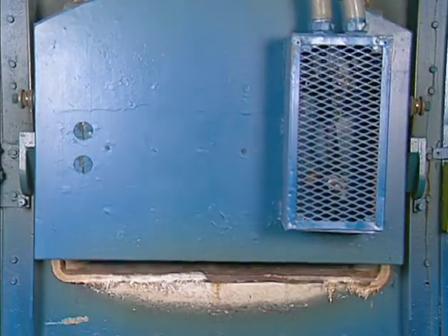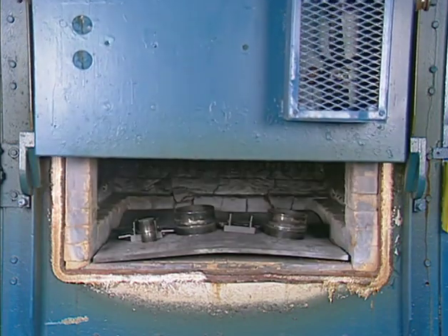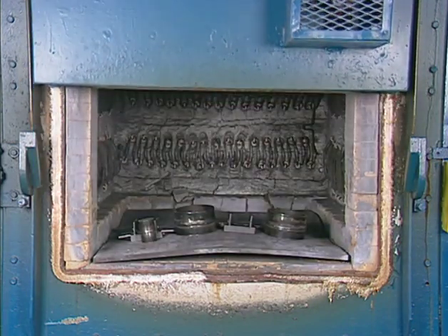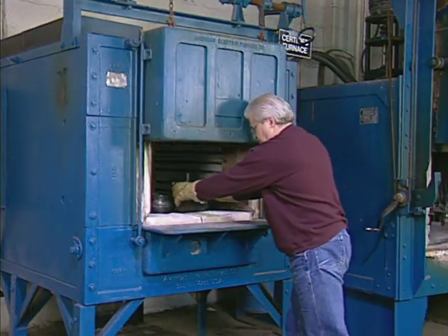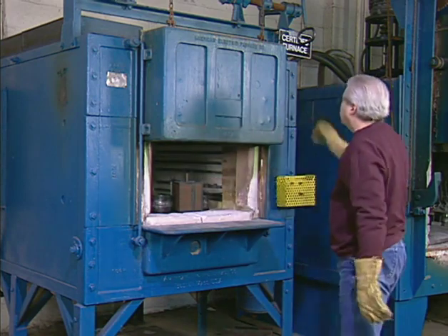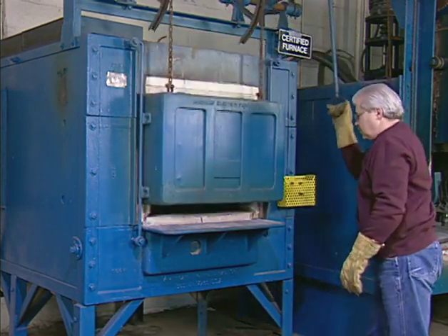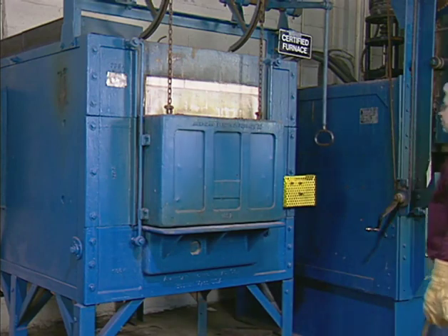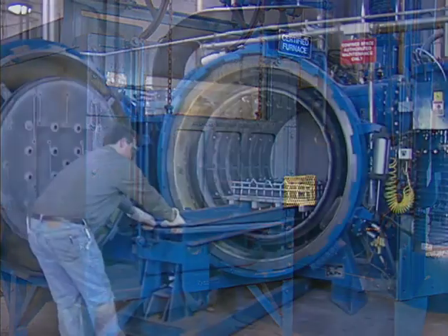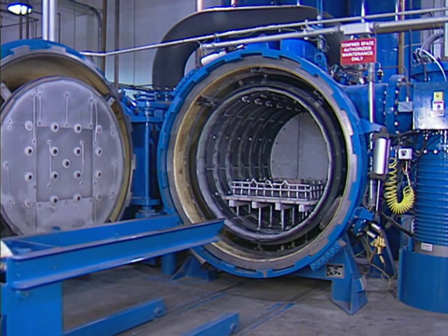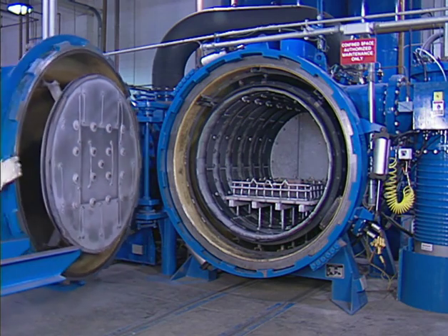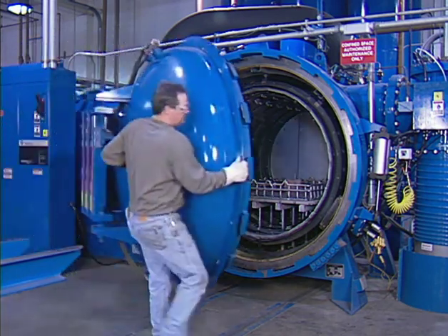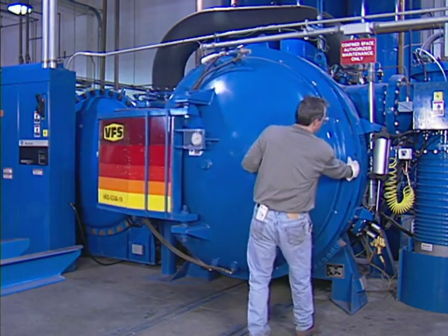Another way to control the cooling rate is through post-weld heat treatments like annealing, normalizing, and stress relieving. Annealing produces softness and high ductility. The weldment is placed in a special oven and the steel is heated into the austenitic range. Then it's left in the oven or placed in an insulated container to cool very slowly. Vacuum ovens are commonly used for annealing because they prevent problems associated with exposing hot metals to the atmosphere, like scaling due to oxidation. And vacuum ovens provide better control of mechanical properties because the cooling cycle can be programmed into the oven.